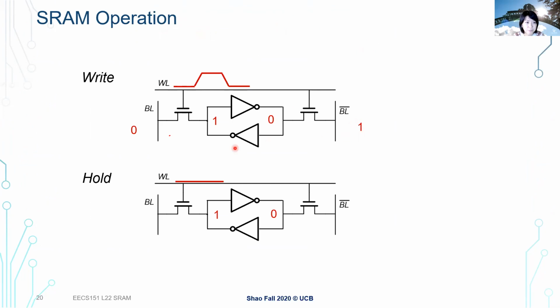So it is 1. Once bit line is 0, this is VDD, and this is VDD, right? If you look at the 3 terminals of our transistor, it's VDD on the gate, so our NMOS transistor is on, and there's also VDD here, and this is ground or 0 here. So what it will do is a discharging operation.